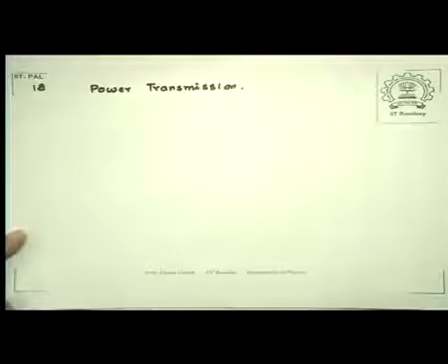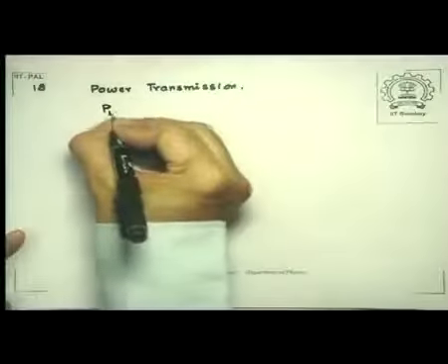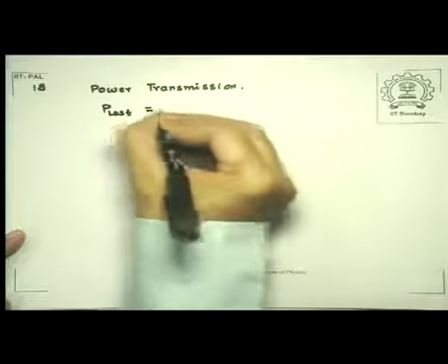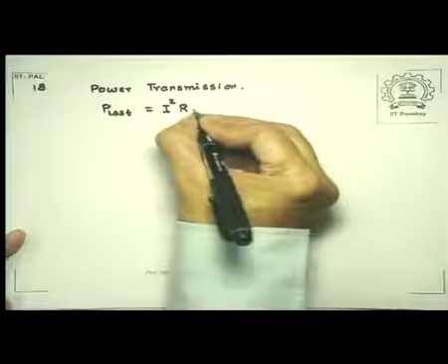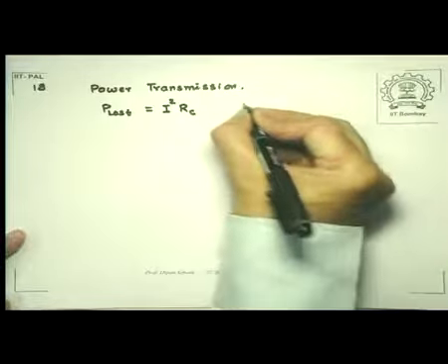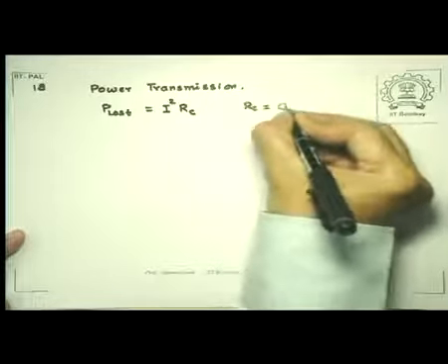Now, because of the fact that the power is produced far away from the cities which actually consume the power, there is a significant loss due to resistance of the cables, and the power lost is given by the current that is flowing squared times the resistance of the cables. Let me write it by RC. So RC is cable resistance.